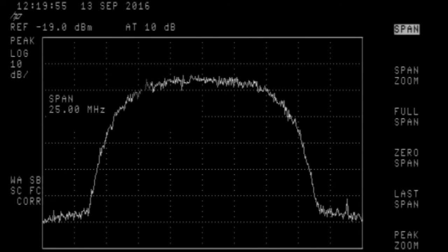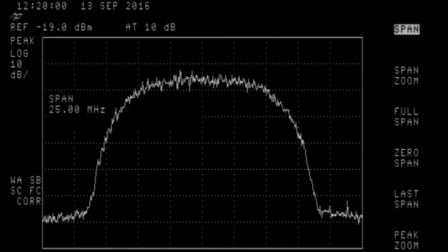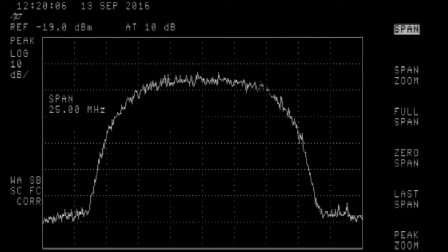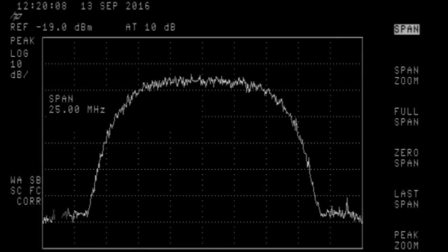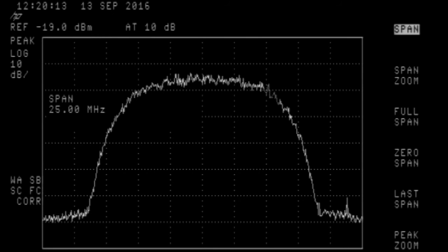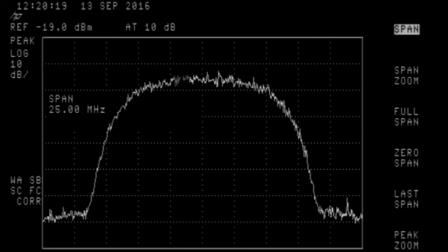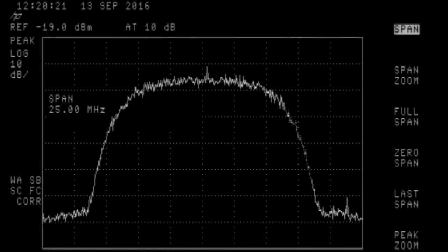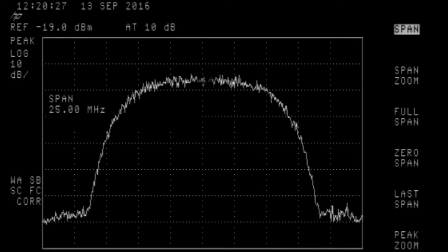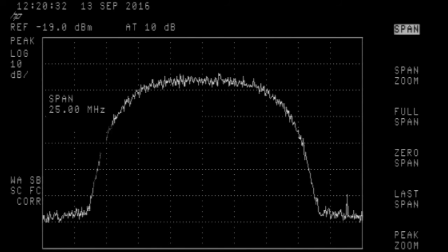Finally, I thought I'd give you one last shot with everything turned up full. This is DATV-BS2 32 APSK 9/10 FEC. Transmitted bitrate is 53.4 megabits per second. CPU usage 42% on my PC. As you'll notice, the spectrum is losing some of its shape, and that's due to the hardware filters on the DATV-Express board. They're actually plus minus 5 meg filters, roll-off 3 dB points I should say.